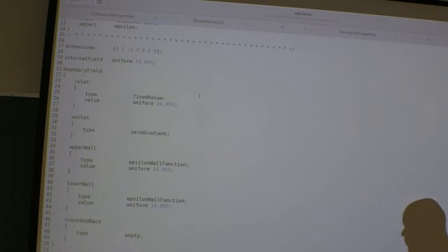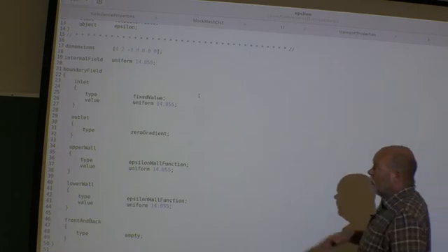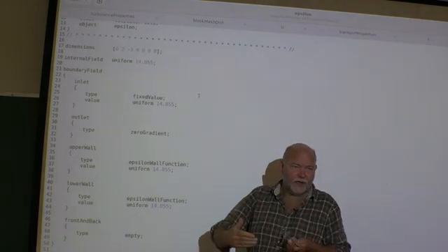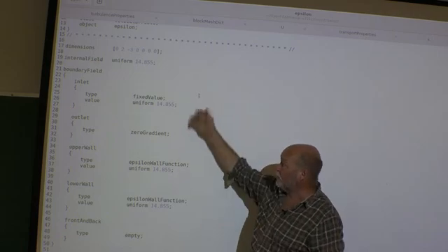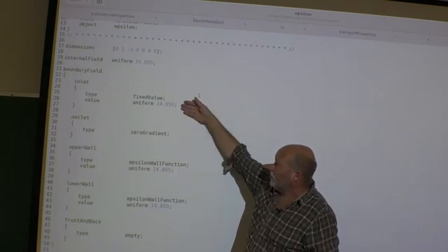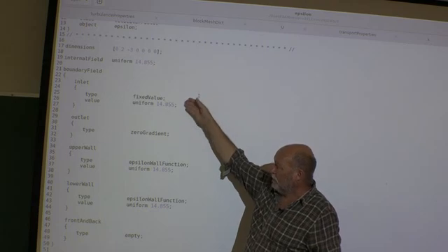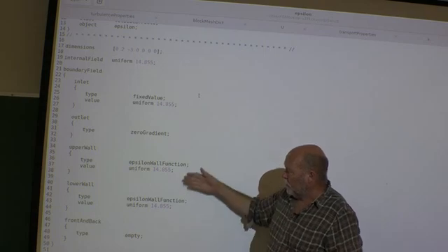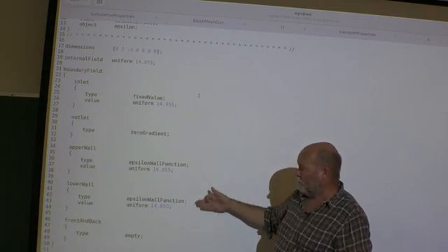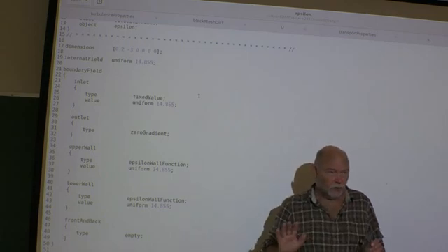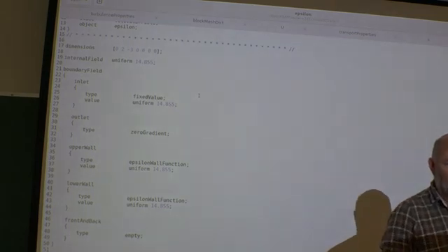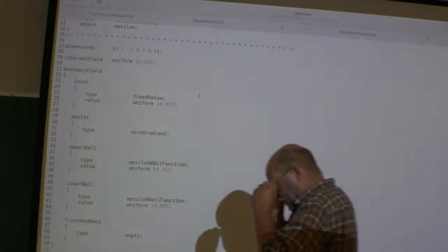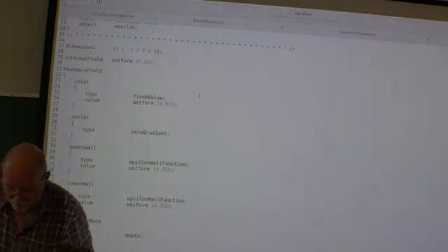The turbulence is going to survive here anyway, I think, but it may converge faster. Remember, we are only interested in the steady state, so get there as fast as possible, so why not? And here again, the same number at the inlet, so close to 15. Then for the walls, also here they used wall functions, meaning y plus should be bigger than 30. Now let's have a look at this y plus thing.